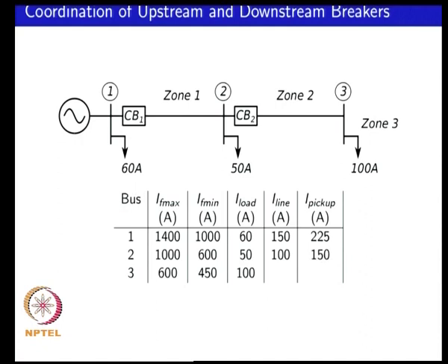You might have transformers that are switching in and out. You might have lines that might be tripping. So, the impedances might be varying over a wide range, and over that entire range it might not be possible to achieve the full coordination. So, you might not be able to meet all these requirements, but your objective is to try and meet as many as possible.